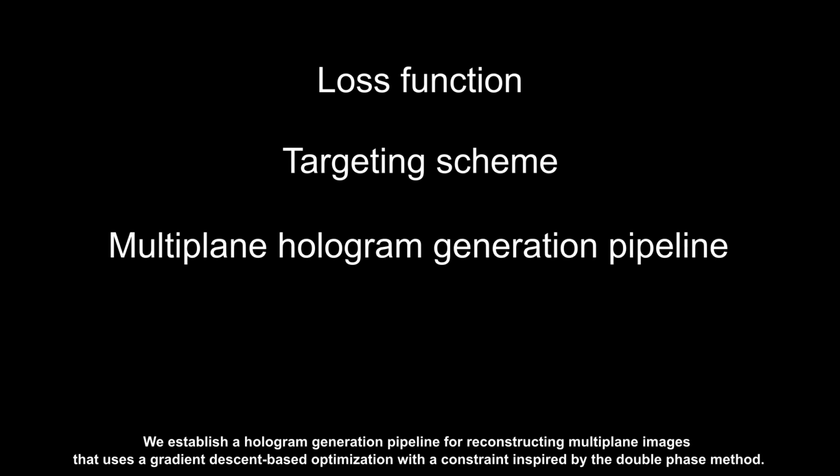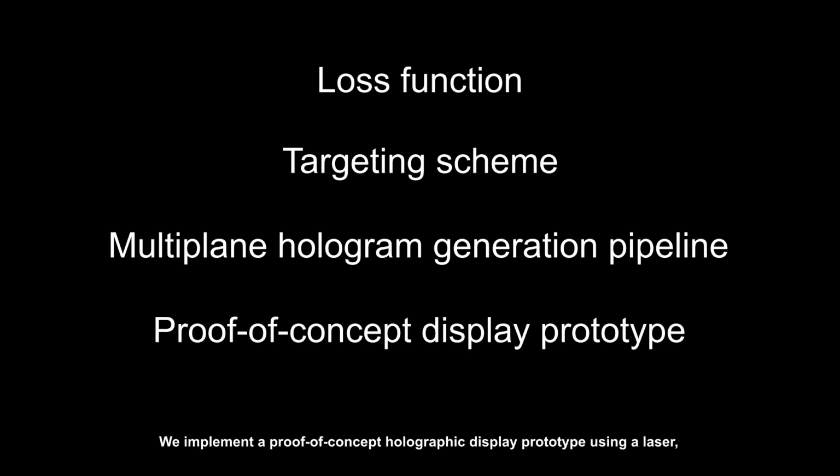We establish a hologram generation pipeline for reconstructing multiplane images that uses a gradient descent-based optimization with a constraint inspired by the double-phase method. We implement a proof-of-concept holographic display prototype using a laser, a phase-only spatial light modulator, conventional optics, and optomechanical parts. We use this prototype as a base for real-life experimentation.